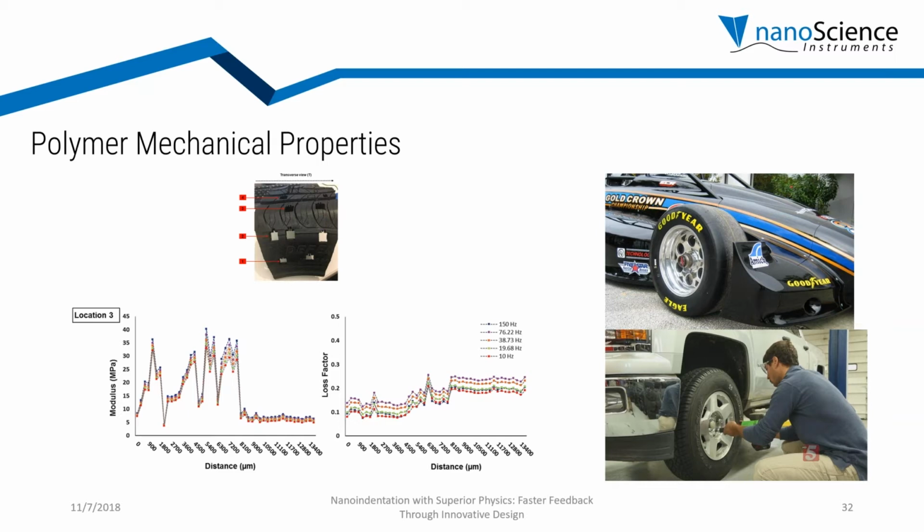They are not all the same, and there's a reason behind that, because a tire needs to be designed based on, let's say, the highest speed the vehicle would go to, or even the weight of the particular vehicle. Now, to design all those tires, you actually have to measure the properties of the tire. You have to understand the viscoelastic response of these tires. So you can perform all these experiments using nanoindentation and very precisely map out the properties on different parts of the tire.